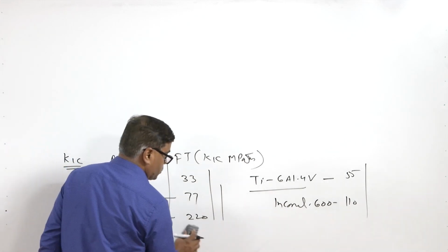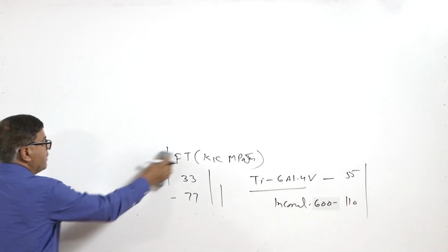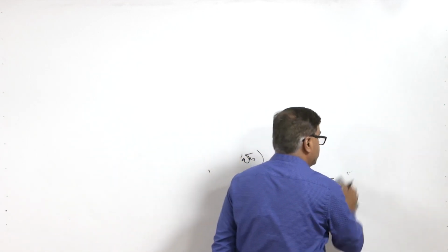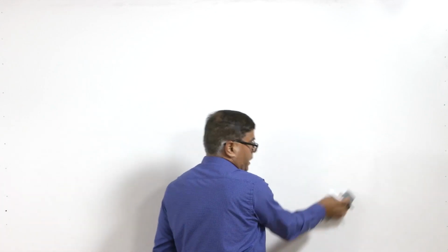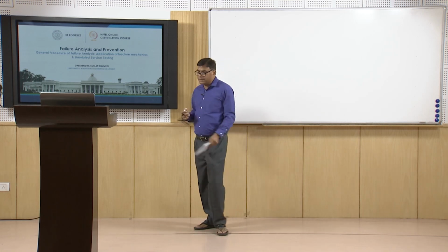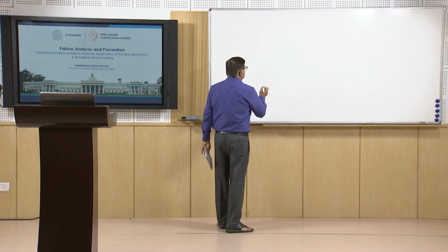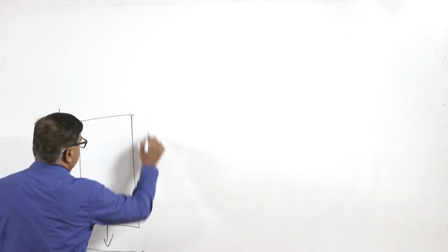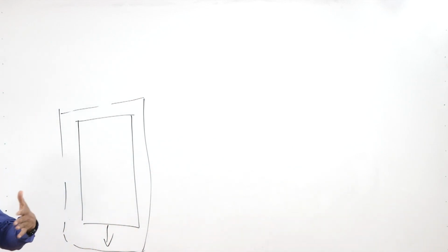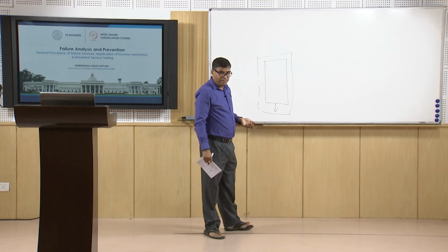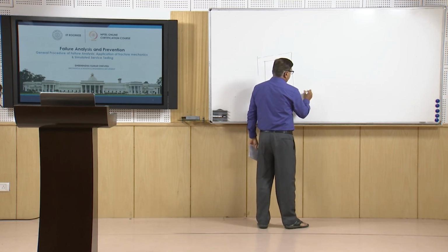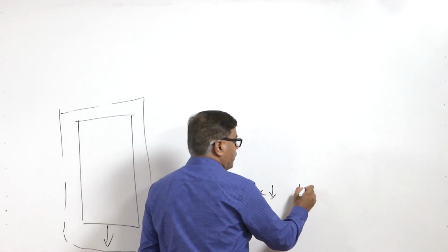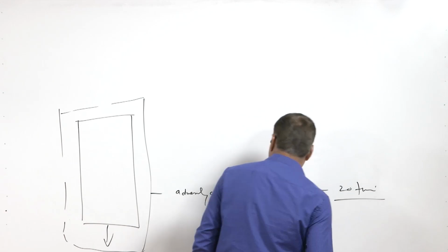When the same component is exposed to corrosive conditions, it behaves in a completely different way. If the design is for dry conditions, or where corrosion possibilities are absent, then these fracture toughness values can be used for developing fracture resistant designs. But if the component is to be exposed to a special environment, different metal systems are sensitive to corrosion in different environments, and it very adversely affects the fracture toughness of the material. K1C is very badly degraded. It may be 10 to 20 times lower than the K1C value under ambient conditions.